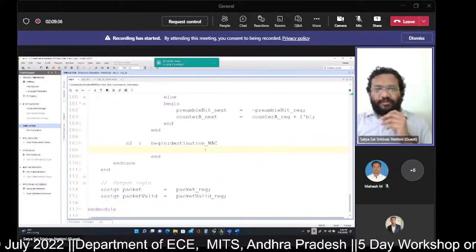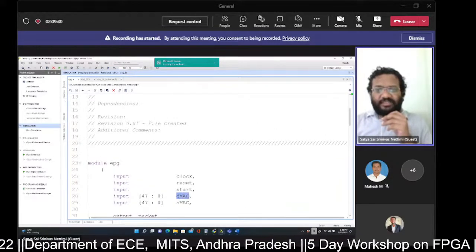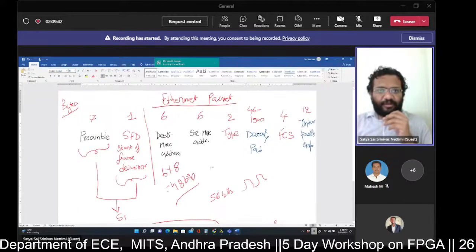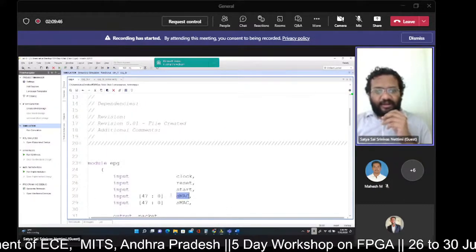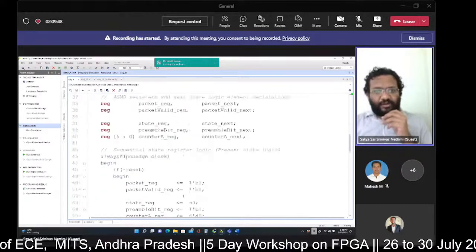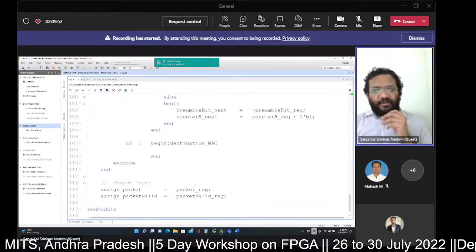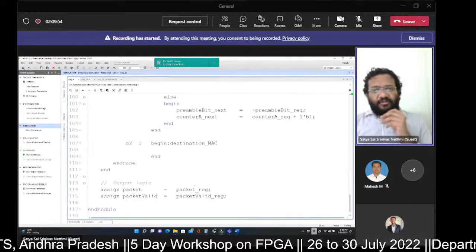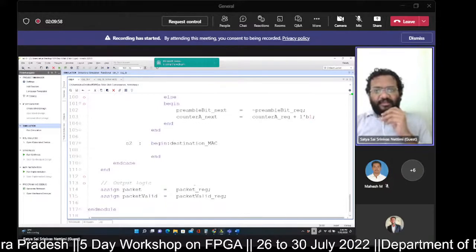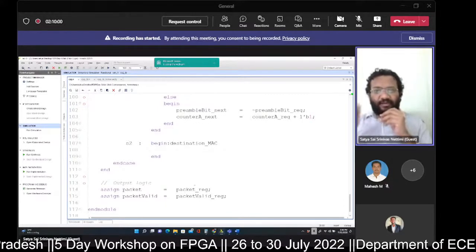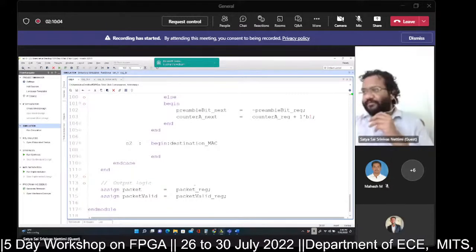Now what I'm supposed to do is read this destination MAC as per the frame format. I need to read the destination MAC address, that is the destination MAC input, and I have to read the entire MAC address and send that MAC address serially onto the output.